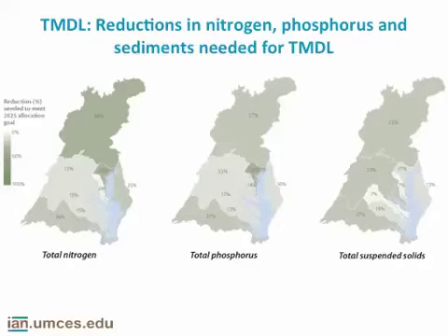You see the urban corridor with high reductions required in the Susquehanna watershed for N and P, but for total suspended solids, it's more of a geographic map of the Piedmont and Ridge and Valley, where the sources of sediments are more pronounced. And you can see that the phosphorus tends to track the total suspended solids a little more closely. For example, the Eastern Shore has got relatively lower percent reduction required because of the low relief and the less runoff.